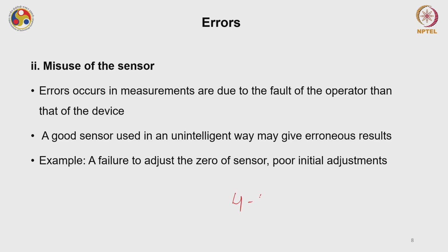Now, even in the condition of this misuse, the idea was to use it between 4 to 40 ppm, right? Now the concentration is say 4000 ppm. What will happen to the sensor? We have discussed that it is not going to fail. What it is going to do is saturate.